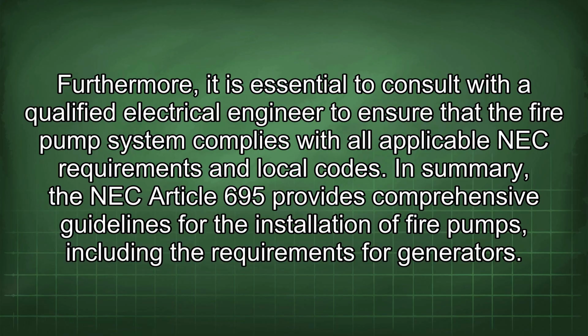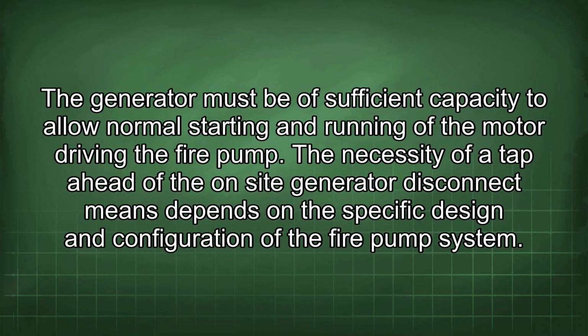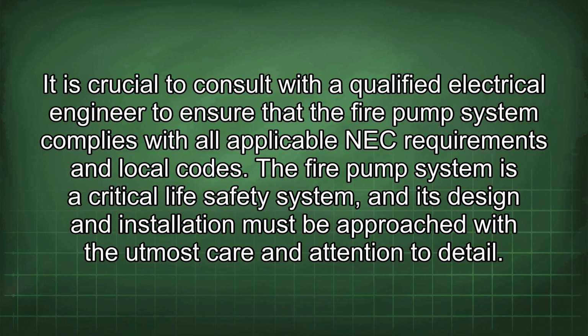In summary, the NEC Article 695 provides comprehensive guidelines for the installation of fire pumps, including the requirements for generators. The generator must be of sufficient capacity to allow normal starting and running of the motor driving the fire pump. The necessity of a tap ahead of the on-site generator disconnect depends on the specific design and configuration of the fire pump system. It is crucial to consult with a qualified electrical engineer to ensure that the fire pump system complies with all applicable NEC requirements and local codes.